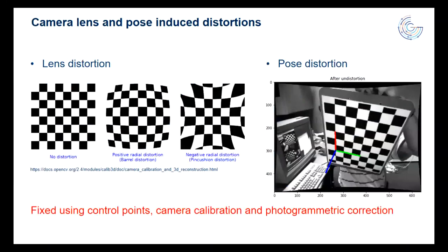So you've gone out, you've bought a camera. You can also specify a lens with a particular focal length in order to get your field of view approximately right with respect to your model position and camera position. And that lens is inevitably going to induce some distortions in the images. Okay, the distortion we can quantify in terms of barrel and pin cushion distortions, and we can fit simple mathematical models to account for these distortions as a function of the coordinates of the pixel that you're looking at within the image. So what I'm looking at here is taking a planar grid on the left-hand side where we've got no distortion, and then I've superposed some distortions here to give you an idea of the sort of distortion that a lens would induce.